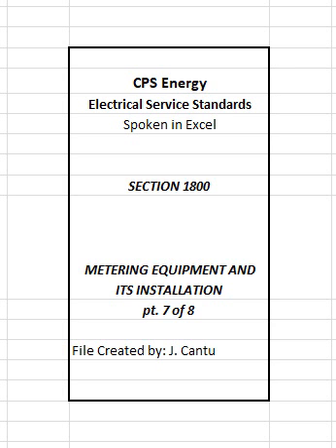2. Mounting of meter sockets and enclosures. Customer shall mount meter sockets and meter enclosures in an approved manner using good workmanship. They must be mounted plumb, level, and be fastened directly to the building or structure using removable steel fasteners that do not rely on plastic or similar non-metallic expansion mounting anchors. Wooden backers may be used when they are a permanent part of a building or structure, and where they are not exposed to the weather.